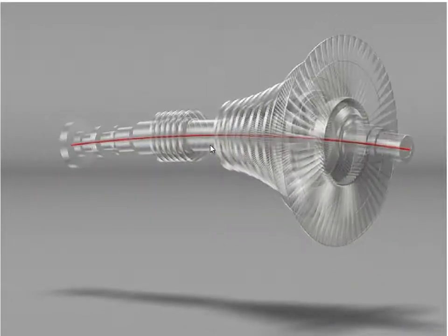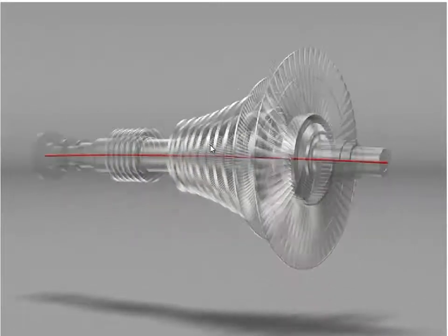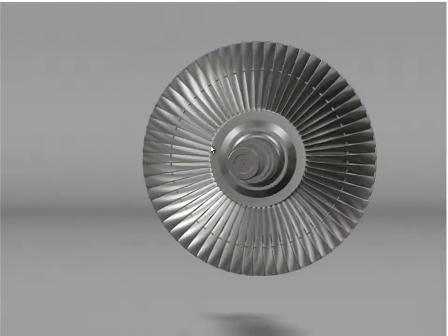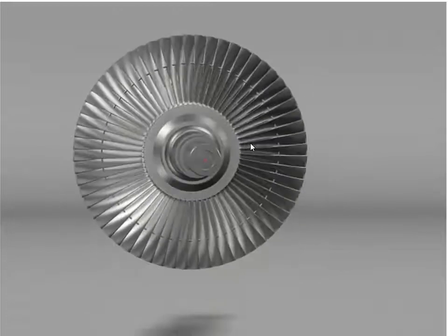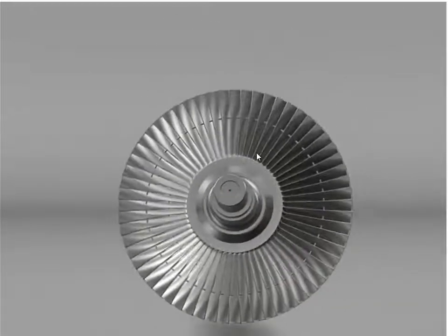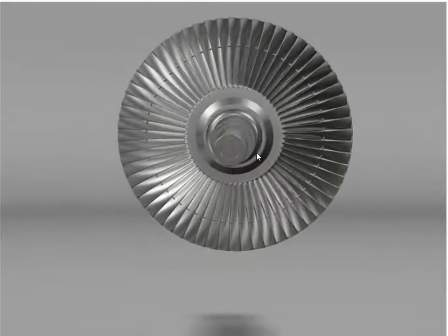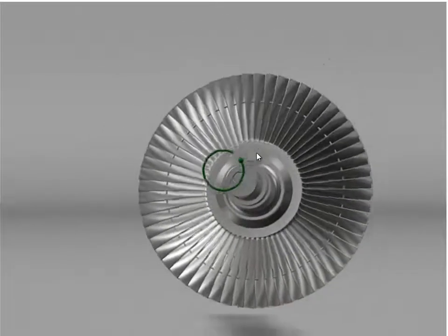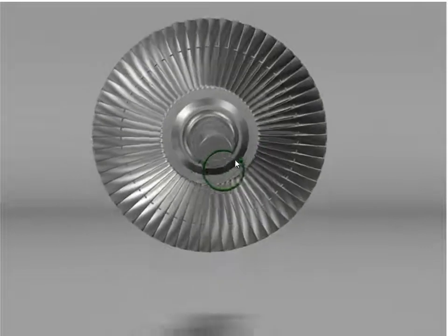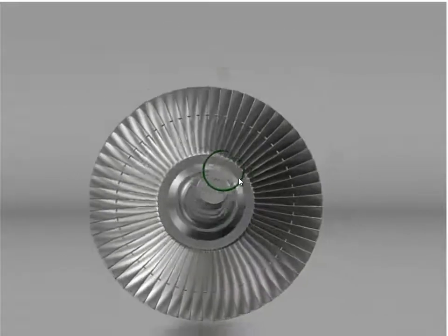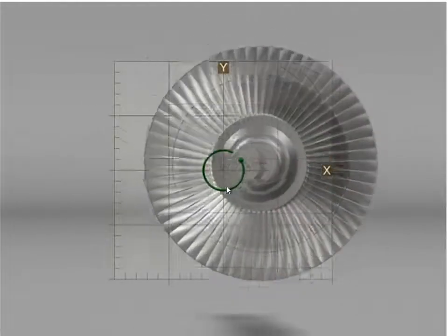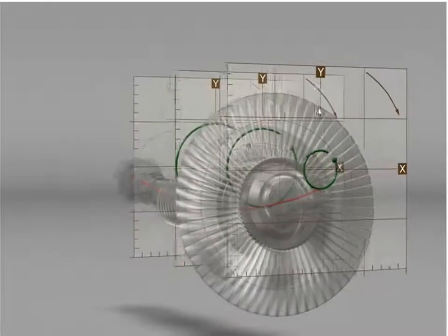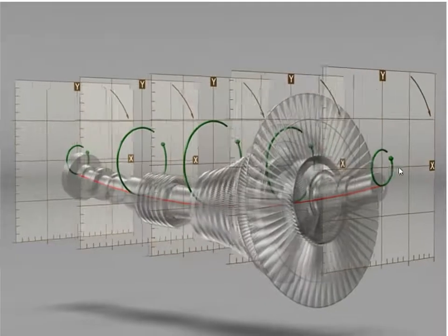A lot of detail we could go into, but I'd be interested in how do I take measurements to tell that's what's going on. Well, imagine if we had our two proximity probes at 90 degrees apart, and they were taking the measurements, and we compared the two sine waves. We end up with a Lissajous figure, as it's often called, or an orbit. We plot the two sine waves against each other. We end up with a circle, if it is moving in a circular motion. And we plot that on a graph, as you can see here, y being the top, x being the side.